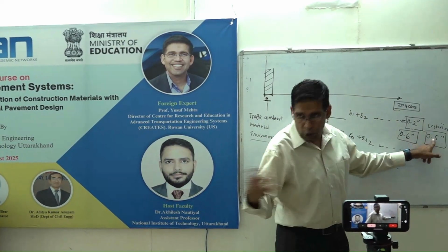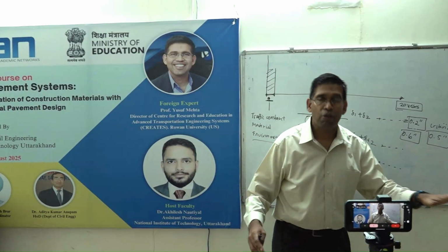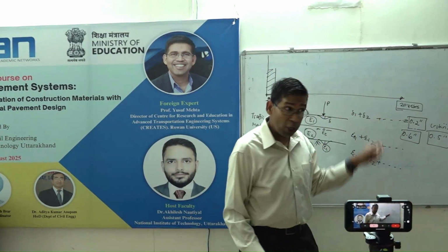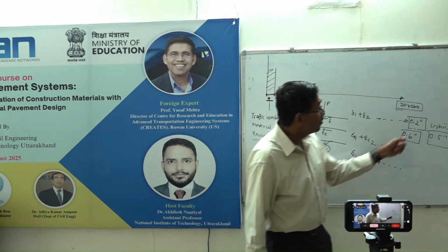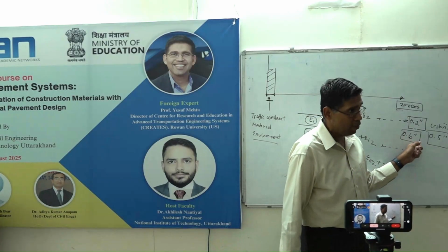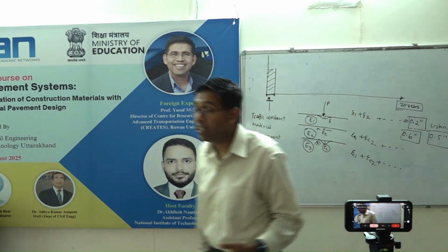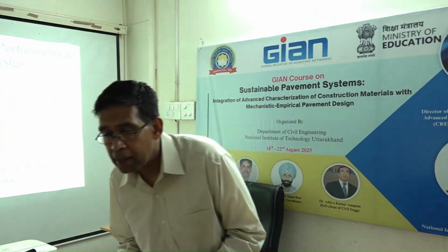That means I'm doing okay. My prediction is less than the criteria. My pavement is fine for rutting. It may not be okay for cracking. It may not be okay for IRI. But if your performance is 0.6 inches, then you have failed the section and you have to redo the analysis. So I did not talk about calibration. I'm assuming that you know that process already. But you have to calibrate eventually. Does that answer your question?